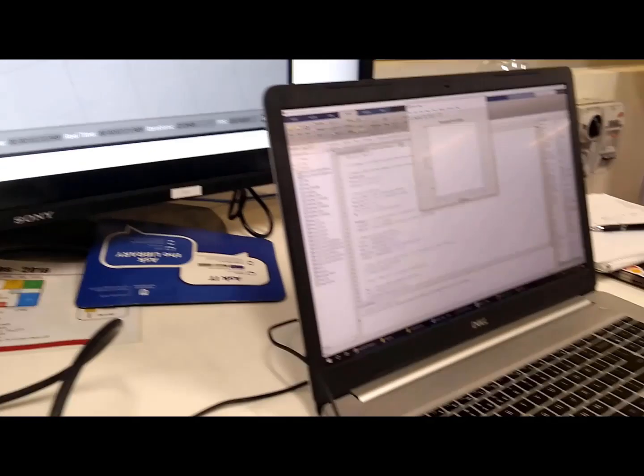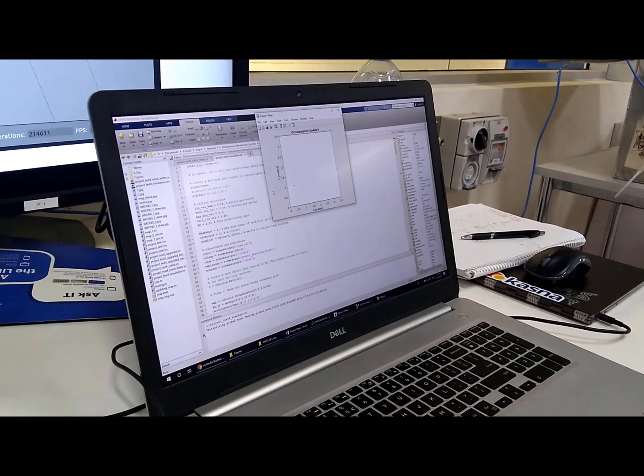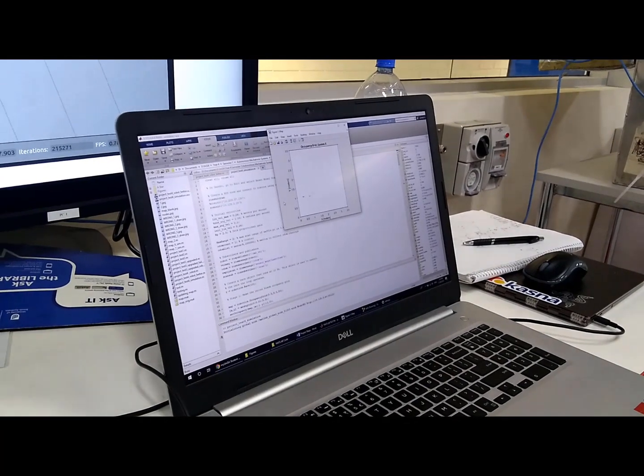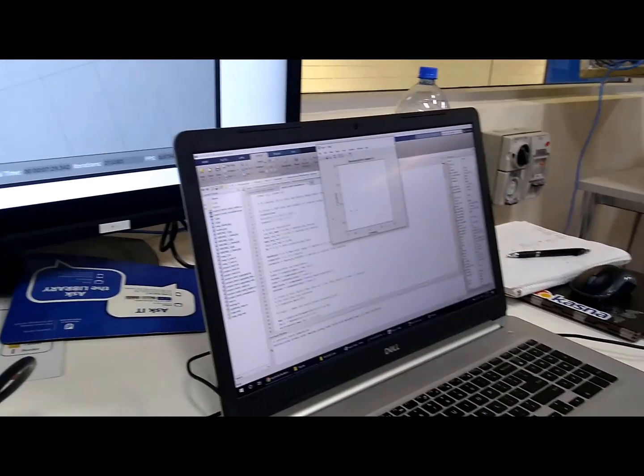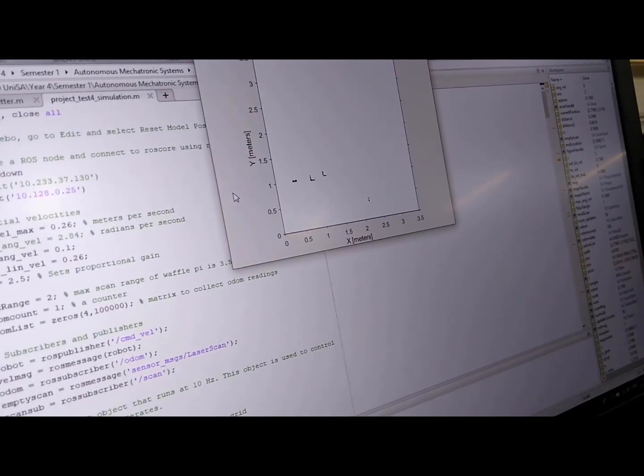It's currently set in simulation for a 2 meter LiDAR scan, not quite as realistic in hardware, but it works well in Gazebo. Every 1 meter it will stop and rescan to adjust for any obstacles that were not within its range or ones that have newly appeared.